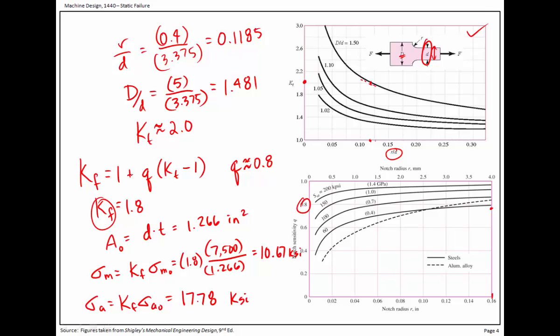I just want to mention that there is a discussion in the text that describes how sometimes, for the mid-range, you don't use the stress concentration factor. I believe the convention is that if you get near the plastic range, then you go ahead and don't use the stress concentration, because I believe the rationale is that you'll have sort of a strain hardening, or a little bit of plastic deformation in the notch. So then the notch doesn't matter as much in the mid-range, right?